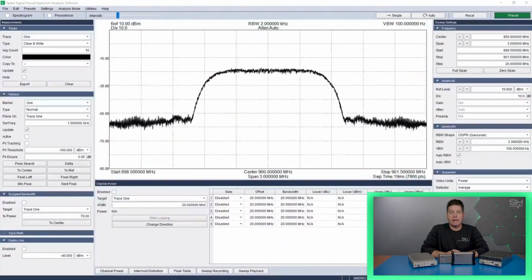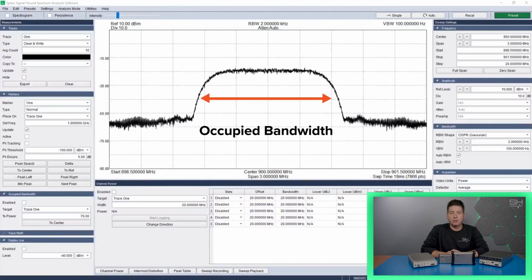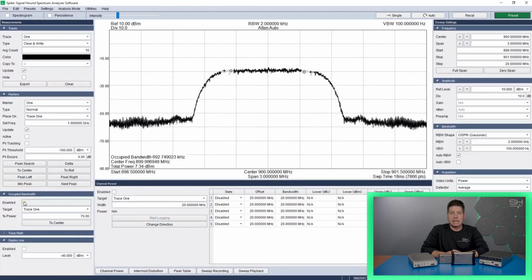As coherent and non-coherent distortion effects can cause spectral regrowth and signal energy leaking into adjacent channels, the extremely broad bandwidth communication standards can be interfered with by even small amounts of signal energy leaking into the band. A measurement of the extent of the frequency at which that signal energy spreads, occupied bandwidth, can be used to maintain standards of communication quality and diagnose degrading communication systems.